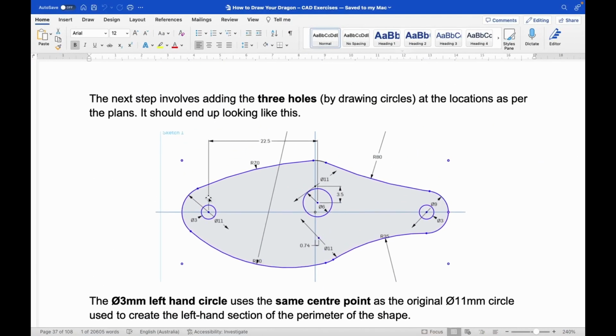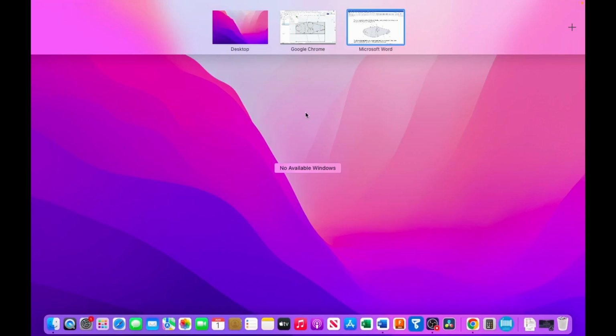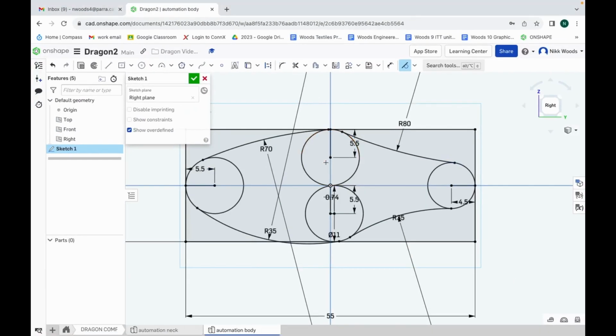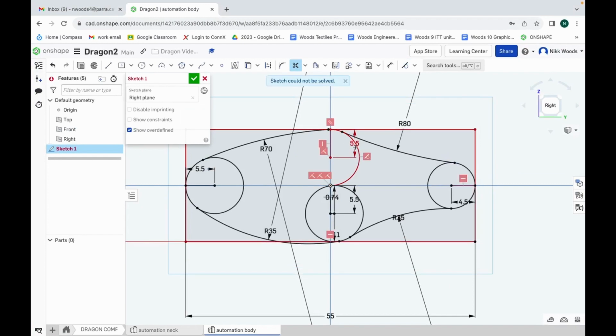Okay, we've got to delete off where all our 4 circles were, and we've got to draw in these 3 circles. So using M on the keyboard to trim. And I'll take off the construction lines as well.